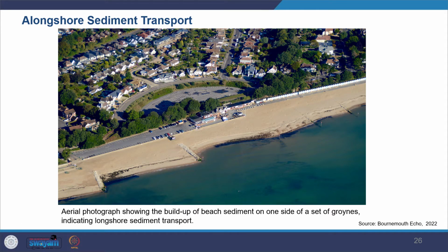So while looking at coastal geomorphology, the interaction between physical processes, the wind, waves, tides, and tidal currents, becomes very important, and they erode, transport and deposit sediments to create landforms. So this understanding is very important, and you need to review alongshore sediment transport in the EIA process. So how is the sediment transport happening along the shore,